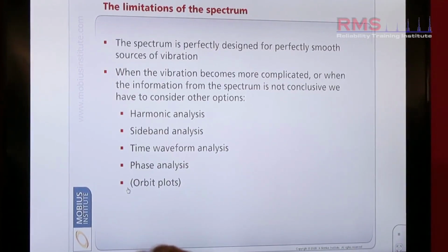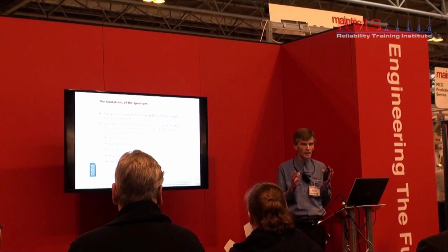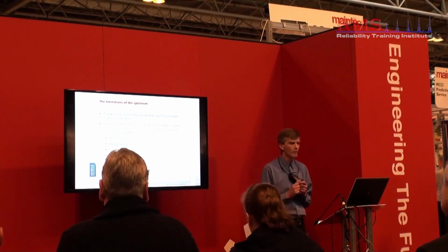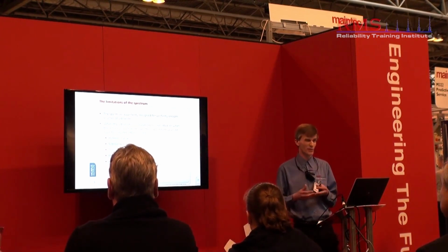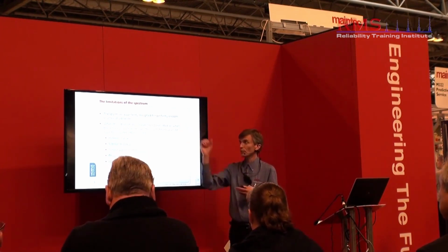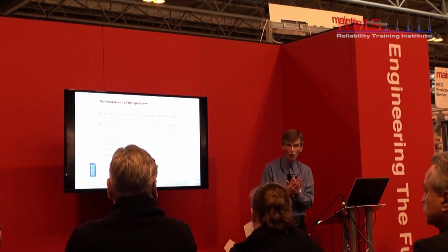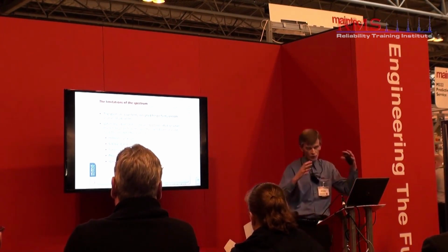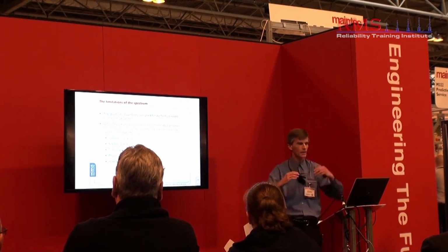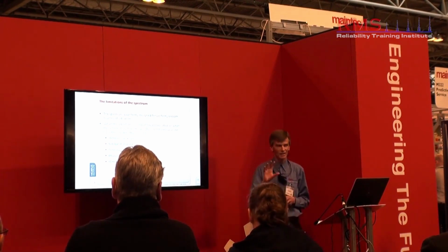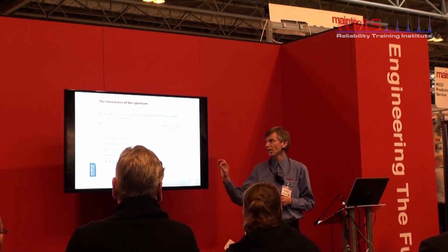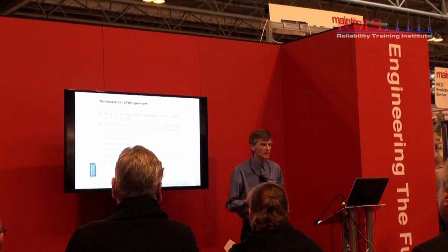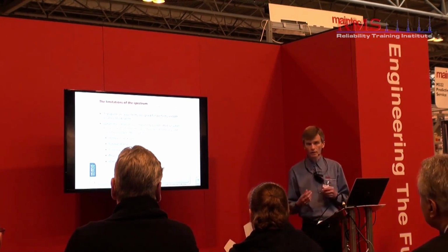Okay, so the spectrum itself works nicely with one single peak, maybe easier, I can look at that and see one peak. But the reality is machines don't produce just pure smooth vibrational forces. Some of them can be shock, we've spoken about those. Some might be pushing and pulling forces against each other, with two shafts fighting each other. So that's going to cause the data to distinctly change. And there are other techniques, which I'm sorry to say we don't have time to cover today, other supplementary techniques that do support the analyst in diagnosing problems.